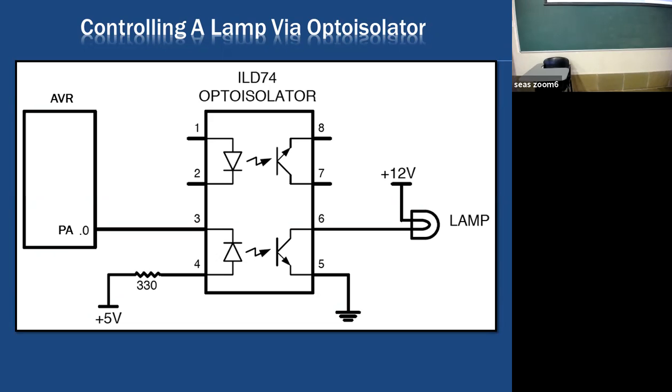So opto isolators must be understood by everyone. You can have a higher voltage here. Now remember that you don't want to connect that higher voltage to any of the pins here, even accidentally, because your pin will have a maximum voltage capacity. And logic 1 is plus 5 volt for our case. So is it clear for everyone? You should understand this thoroughly. And this is just an integrated circuit with two of these pairs. This is not connected, so if it is not connected, you don't worry. This is connected, so you understand this. So is it clear with everyone? That is how it is working.